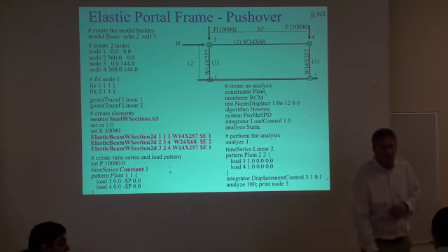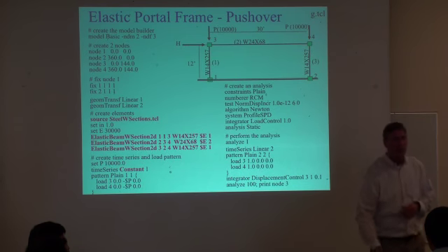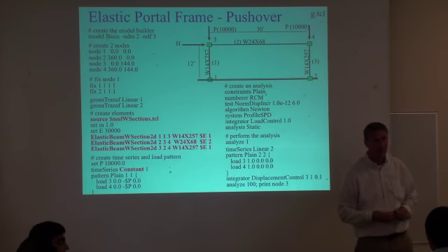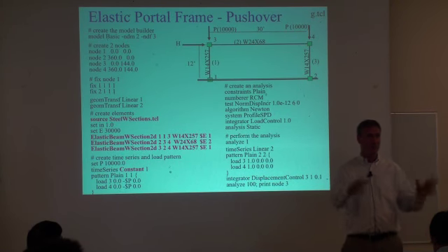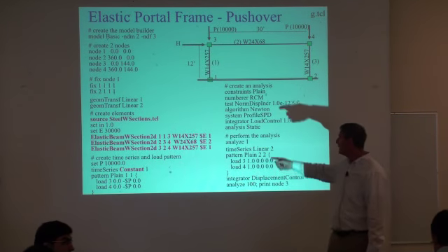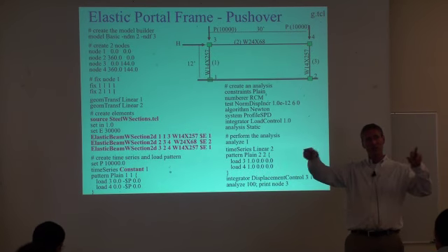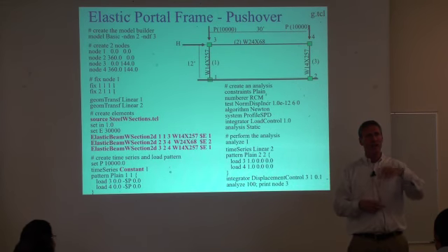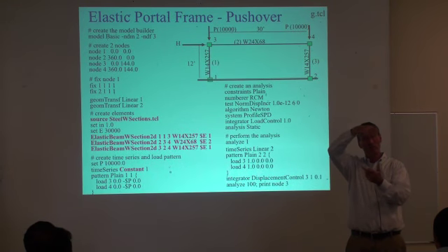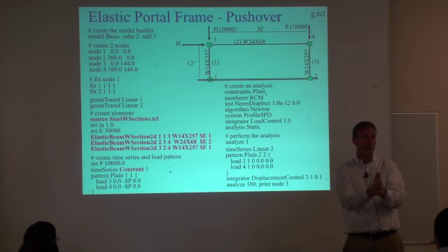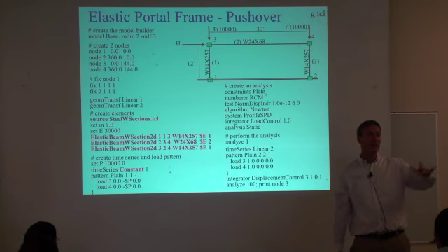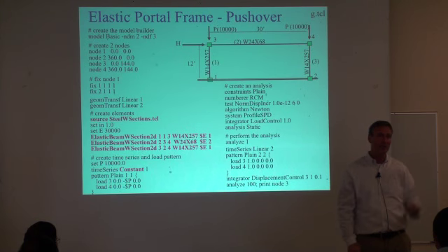Can we apply moving load? Yes, you can. I will get Michael Scott to talk about it this afternoon. He's done it in two ways. I believe you can do it in the script, inside the loop, by adding a new load pattern every time, in which he changes where the load is being applied, either moving the point load along the element. Each time step, that load is getting changed, and he does that in the script. He might also have coded it into the program itself, where the load moves along the elements.